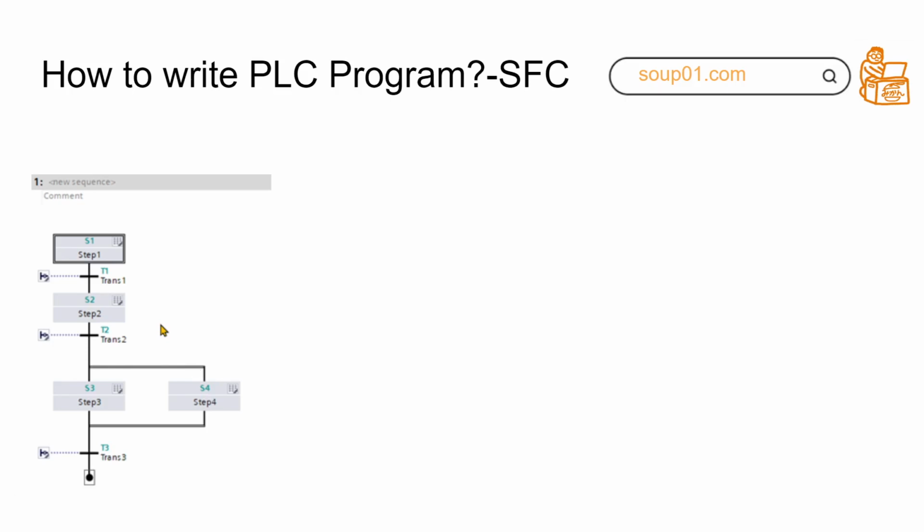You can get the flowchart from the customer. You can just draw, like drawing, and then write your program. But with this type of program, you may waste so much memory because each step will have its own status. For example, they have a step, they will have their action, they will have their condition. So many things, they need to keep so many flags, so they may spend more memory. But it's easy to read because you can actually see what your current step is in graphic.